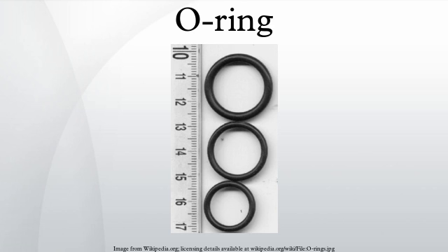Surface finish is also especially important in dynamic applications. A surface finish that is too rough will abrade the surface of the O-ring, and a surface that is too smooth will not allow the seal to be adequately lubricated by a fluid film.